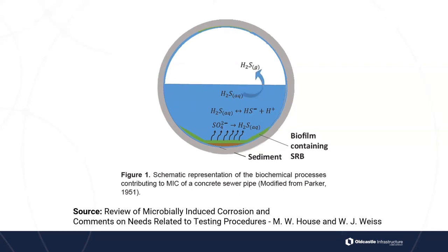Now, keep in mind that typical pH values of municipal wastewater range from 6.0 to 8.0. So somewhere between 6 and 8 pH, it could be slightly acidic or slightly basic there. But this disproves the idea that the water is highly acidic and corrodes the concrete itself, because a pH of 6 is not enough to corrode concrete.